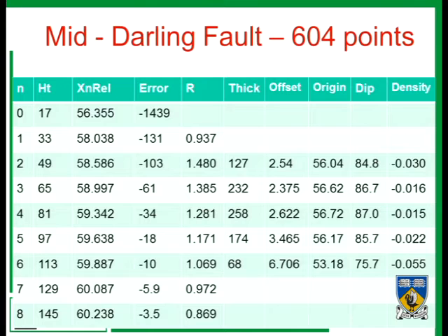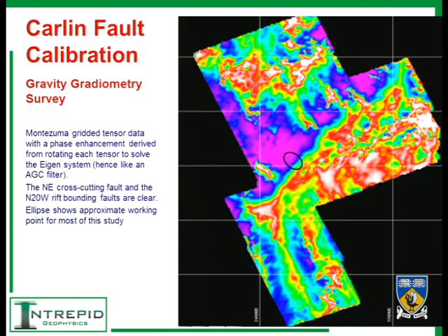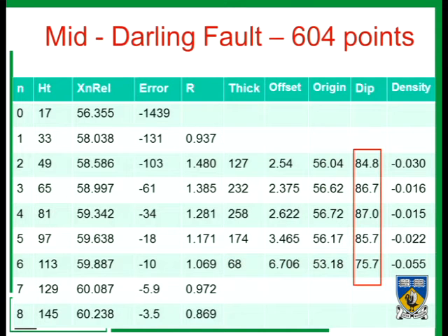This is in kilometres. Everything's in kilometres the way that the thing was done, and you get an error term, you get a correlation term, and you get the different continuation, and here you get your dip estimates at that particular point. So you see there's a mean plus a sort of a standard deviation sitting there. So that's my summary discussion of the scalar gravity piece of work.